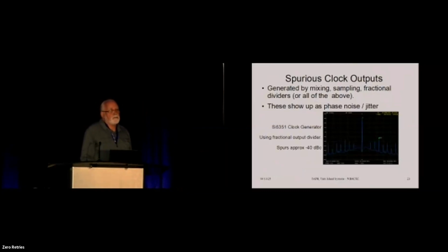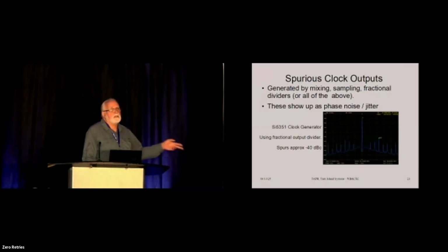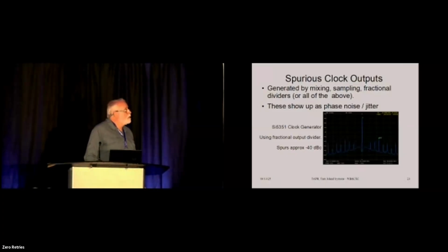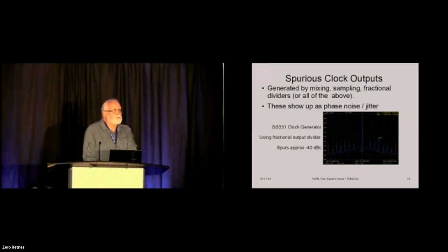If we have a clock source, ideally it would be a perfect sine wave, no sidebands. Harmonics maybe don't matter that much for a local oscillator, depending on how you filter it. For an analog-to-digital sample clock, harmonically related spurs probably aren't a problem. I mean, a square wave's got a ton of odd harmonics. But these are non-harmonically related spurs, these sidebands on the spectrum there.